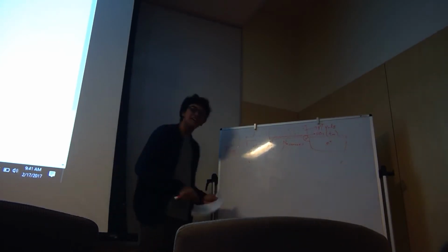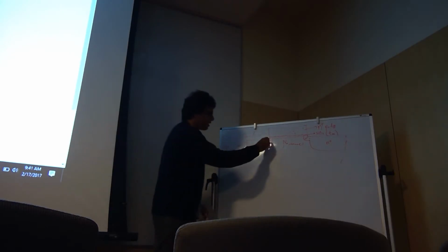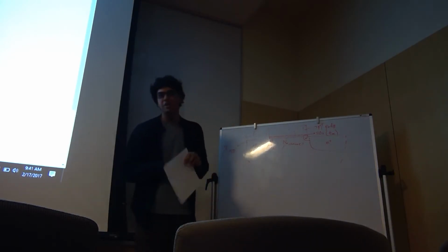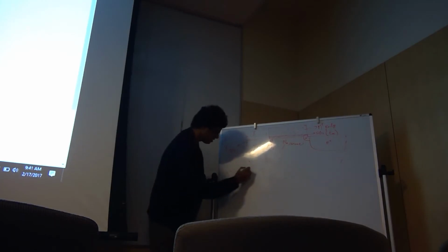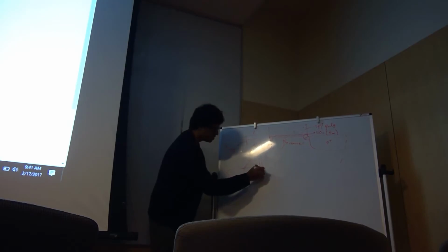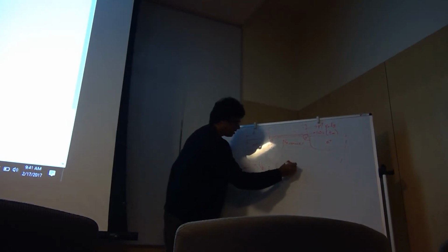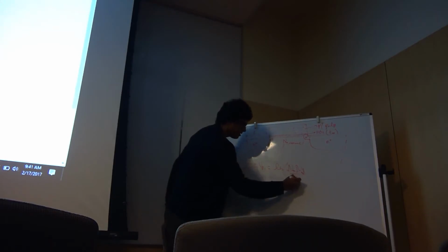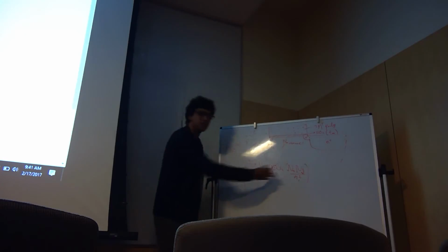Actually, you know what? Why do you dope that little area lightly? Why don't you dope the entire thing heavily? So the reason, okay, you all know how a PN junction works, right? When you have a PN junction, the built-in potential here is usually some logarithm function of the product of the dopings here and here. So it will be something like kT over q.